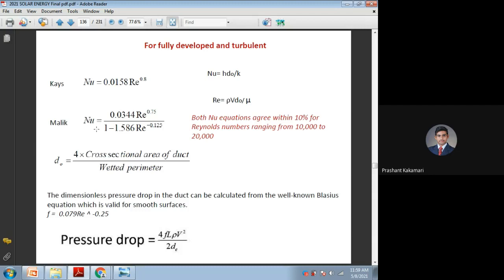So why are we using Nusselt number? Because without knowing this h value, D value or k value, one can find out Nusselt number directly by Reynolds number. That's one advantage. Once you find out this Nusselt number, if anything is unknown in these equations, any one unknown value can be found by the hL by k equation or hD0 by k here.